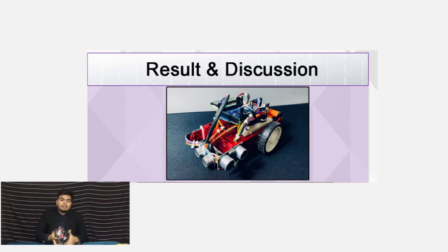For the battery, I use two pieces of lithium-ion 3.7 volt attached at the back of the robot. For measuring the distance traveled by the robot, I use the encoder sensor module attached at the bottom of the robot, aligned properly with the grip plate. This chassis is made of aluminium and equipped with wheels of 65 mm diameter. For the display, I use a 16x2 with an I2C module attached at the side, so the display will show the measurement or distance traveled by the robot.